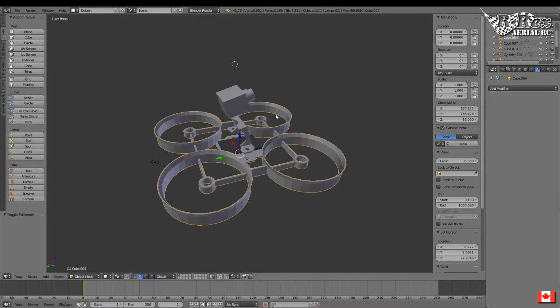Now, when you're printing an object like this, it's probably going to warp on the bed. So when you print it, you're going to want to print it with a brim around the outside of the object so that it adds more surface area to hold these thin surfaces to the actual print bed. But with most slicers, they only add brim around the outside of the object, which means there's not going to be any brim on the inside here or on the inside of here. So these will actually curl up. Now there's a really easy fix for that. Usually I print my first layer at about 0.4 millimeters. It's pretty thick, but it allows it to be more squishy and adhere better.